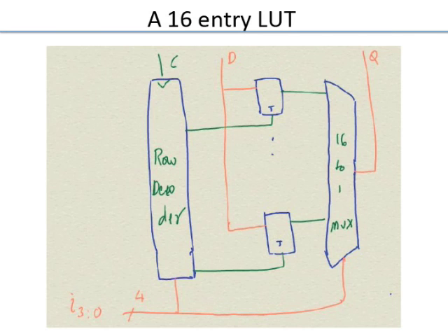After that, once the write enable goes away, I don't have that. Now I can achieve that by having the write enable go high and come down for that cycle. So then you put it always in the read mode. The memory is always in the read mode. When you want to write, you turn it on for that one cycle, it writes. So instead of a clock, you can have the write enable.